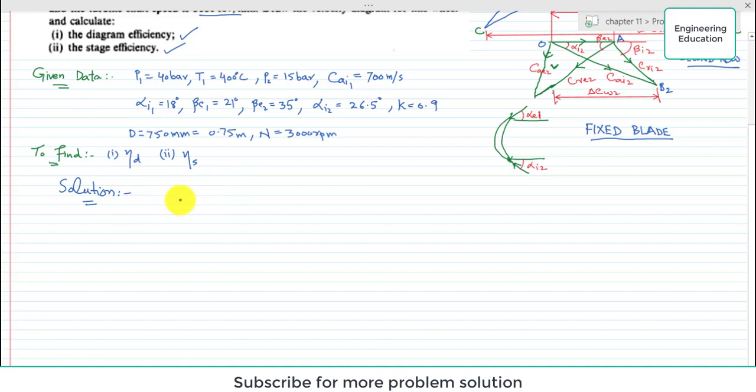So first of all, we will find the blade speed, that is R omega or R into 2 pi n by 60. R is nothing but d by 2.